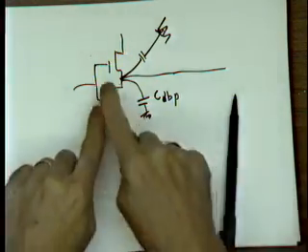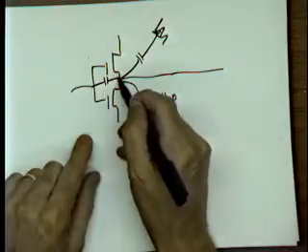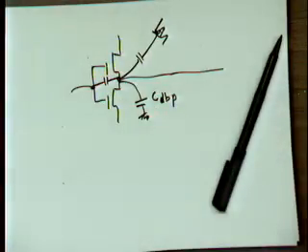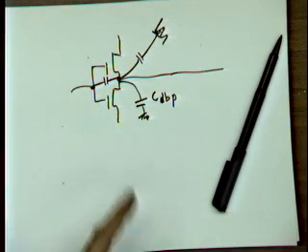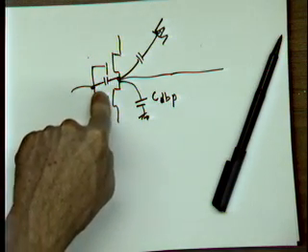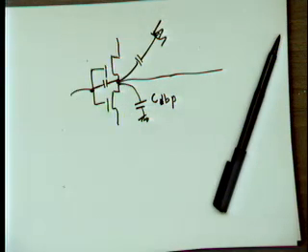we have a problem. That's like this capacitor here, which we call the Miller capacitance. That's a nasty one. It's a floating capacitance, and you move one node in one direction, the other one goes the other way. And that's another story. In order to turn that into capacitance to ground, you have to use this Miller equivalent type of equation. Okay?